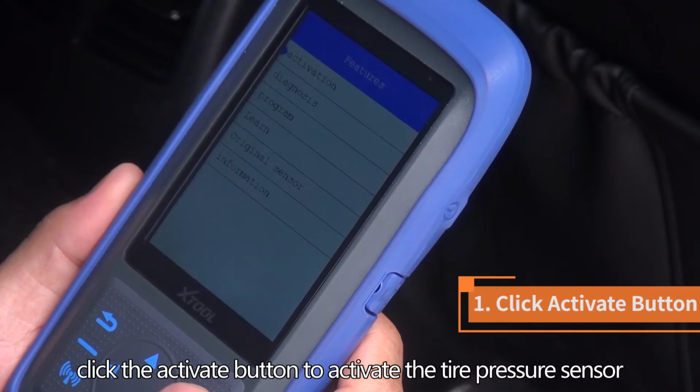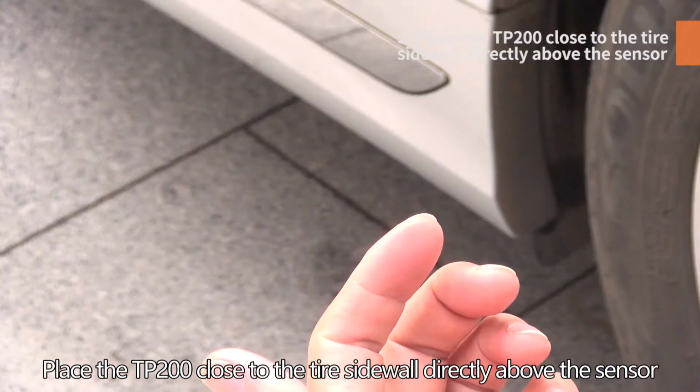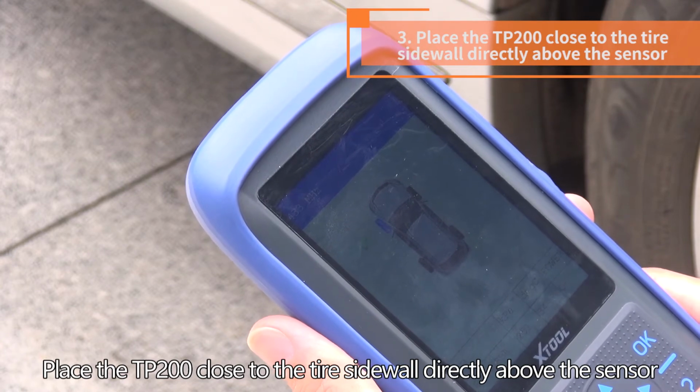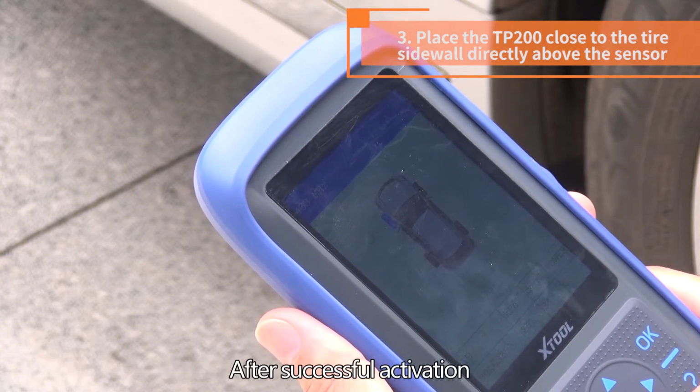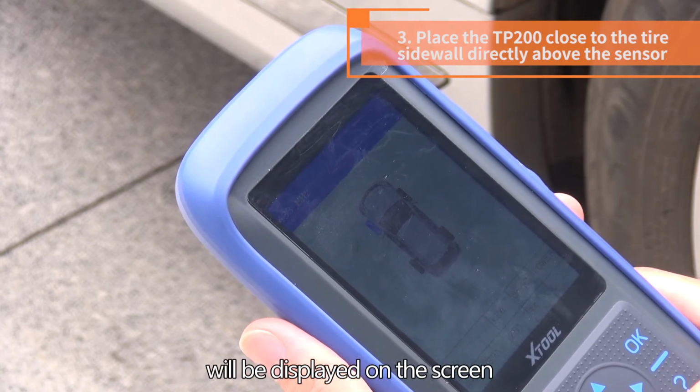Click the Activate button to activate the tire pressure sensor. Use the arrow keys to select different tires, and place the TP200 close to the tire sidewall directly above the sensor. After successful activation, the status and pressure value of the sensor will be displayed on the screen.